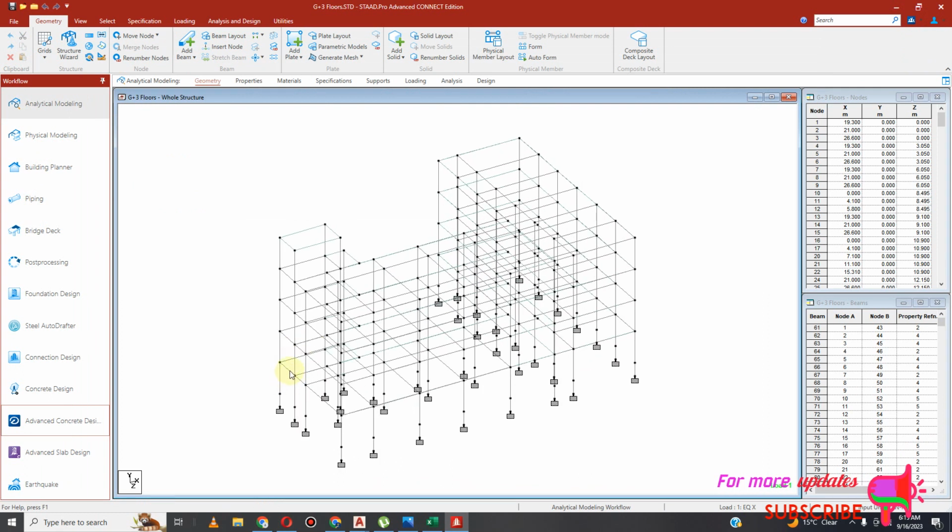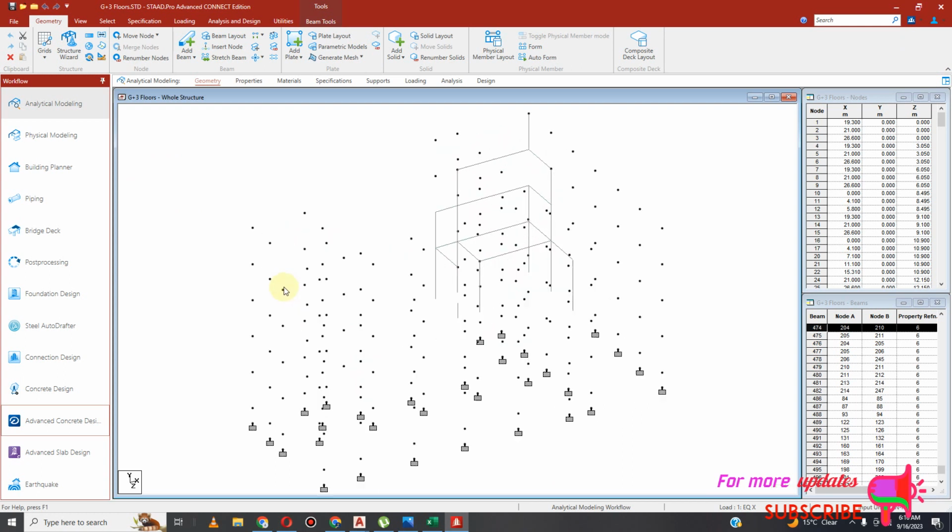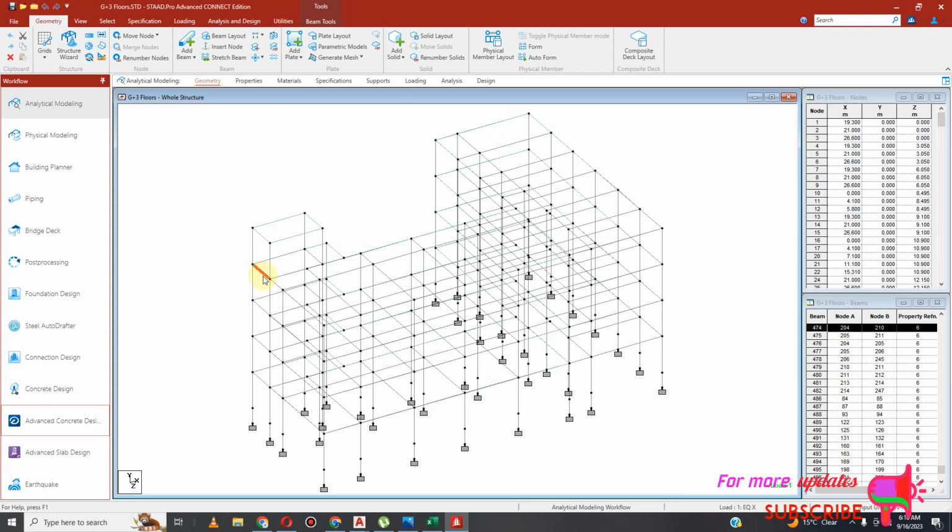Remember, I have staircase here. Okay, before I go to Slab and staircase, and just add here a lot of... you can just do, but already we designed this column to be bigger in size than the rest, so the design will still be okay, but remember to add here a load of 11, that is the 22 kilonewtons per meter for the weight of the slab of the stairs.